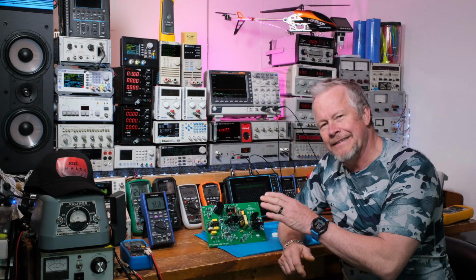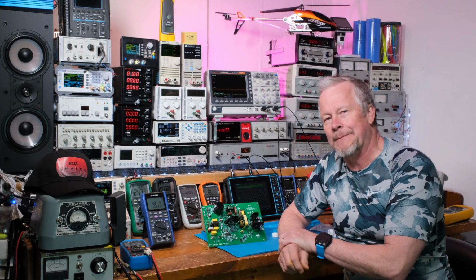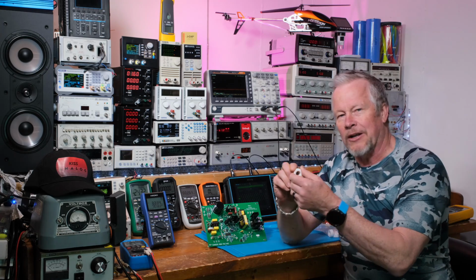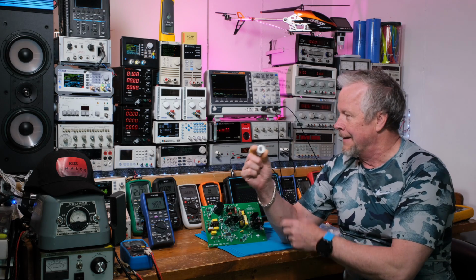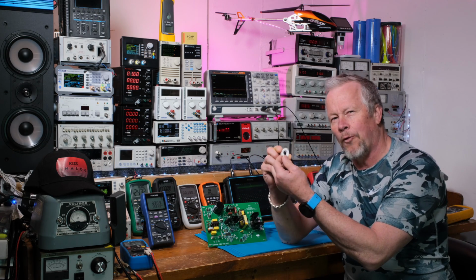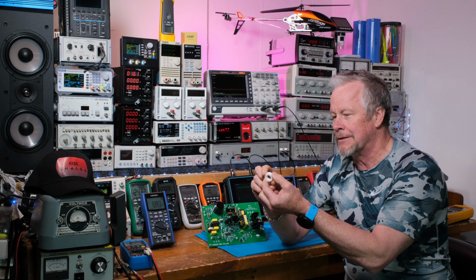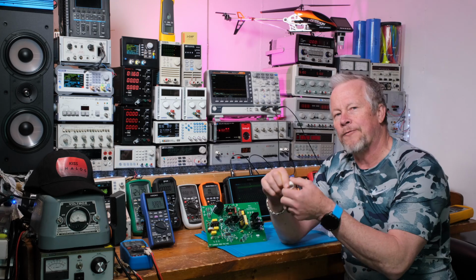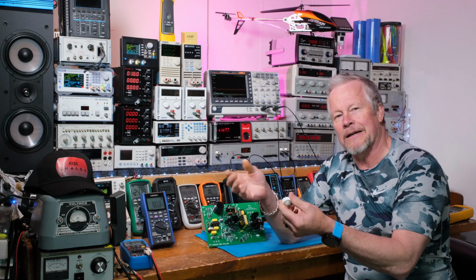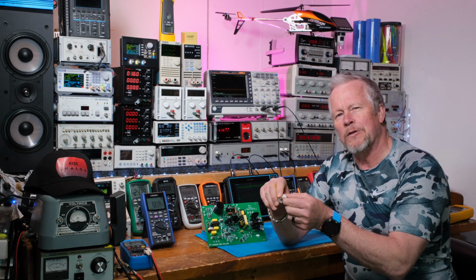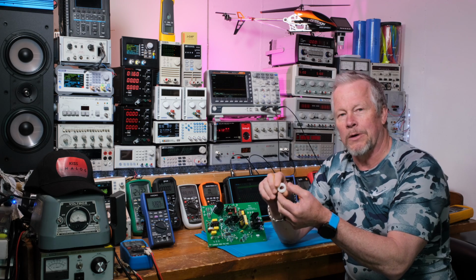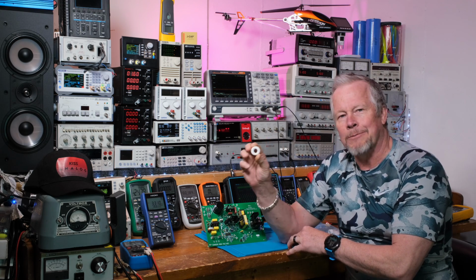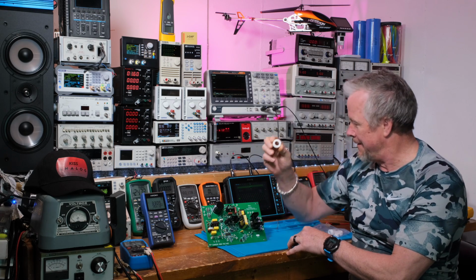And there's actually, they look different. I mean, they come in different varieties. One of them is on a toroid, like on a core like this, okay? Now, there's special cores for common mode chokes for EMI filters. You use a different core than you would for, say, a differential choke, or just an inductor that you might use for filtering, which would be more referred to as a differential or normal mode choke, where it's kind of the opposite of the common mode choke, okay?